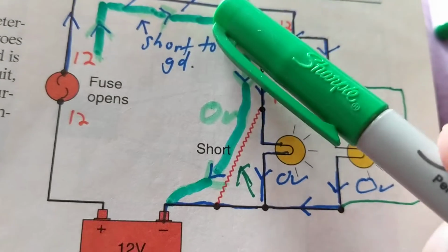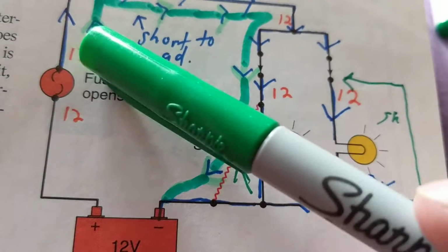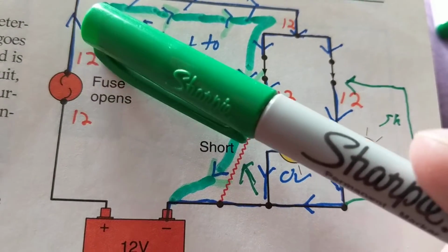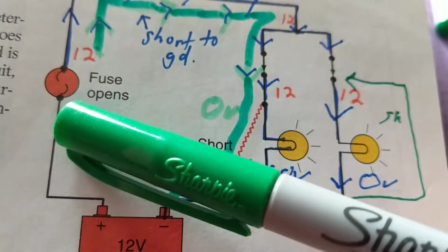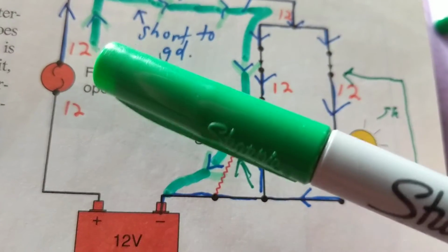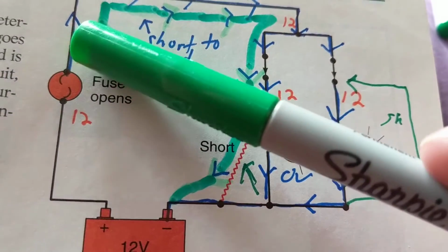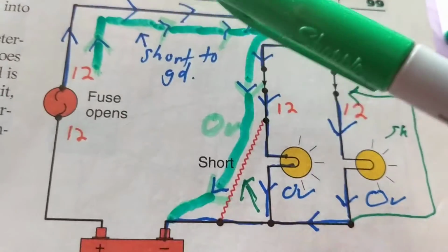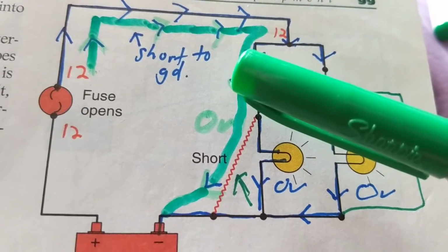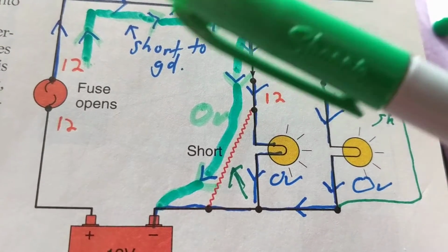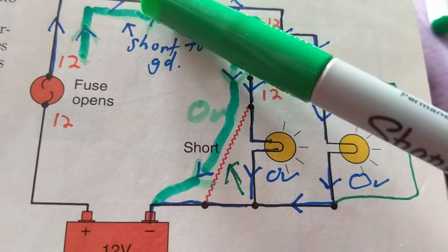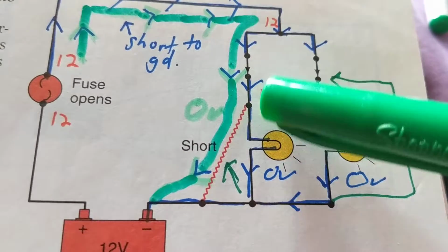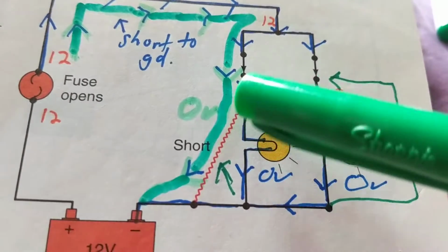We have a big problem. We have a short to ground. What do? Ohm meter. Ohms. On the other side of the fuse, like I will show you on a hands-on, if we want to measure ohms, we don't go over here, we measure over here, because the load is on this side. That's what's blowing the fuse. We go from here to here, put on ohms, like I'll show you hopefully in the video, and we'll measure 0 ohms. We take out this light, and then we see which one it is. That's if the short is here.